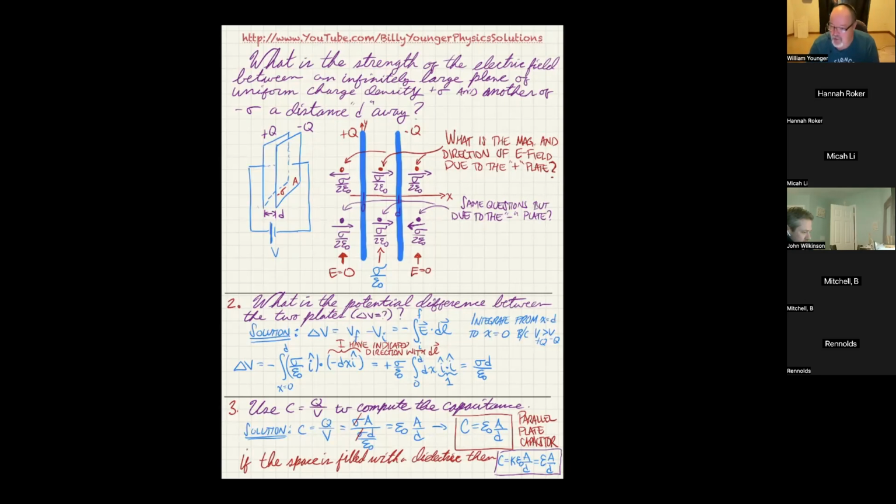So it turns out you can make a really big sheet of, let's say, mylar or some other conductive material like aluminum foil. And then on top of that sheet, you can stick a piece of lucite or some other insulating material that ideally would be able to bend. You can lay that down on top of the aluminum, covering up the whole aluminum foil, and then lay the other sheet of aluminum foil down, connect a wire to one sheet and a different wire to the other sheet of aluminum.